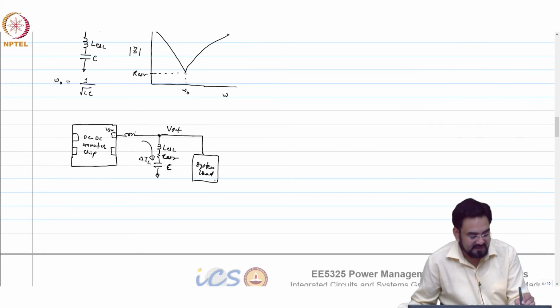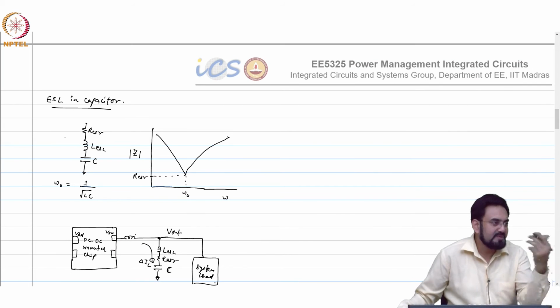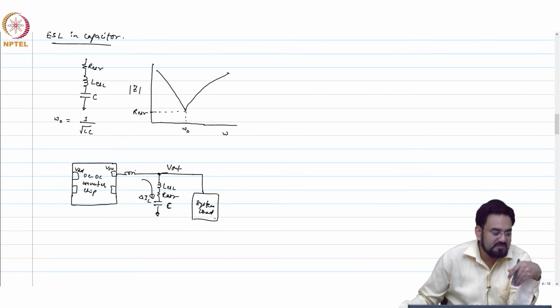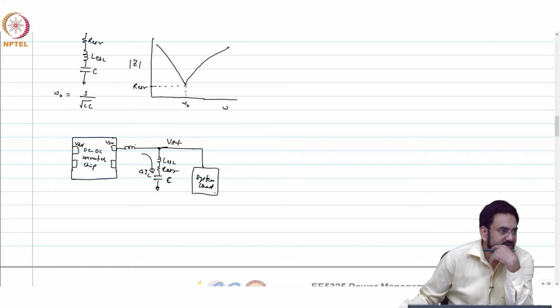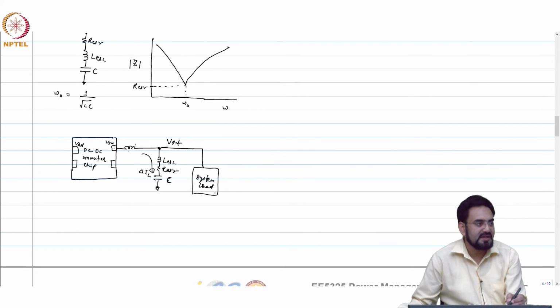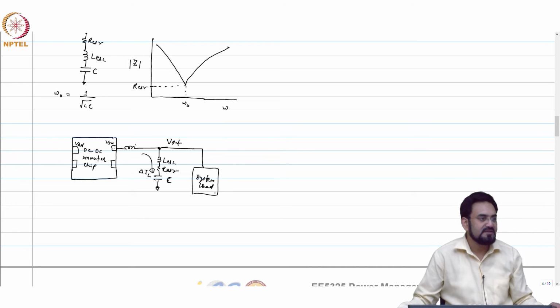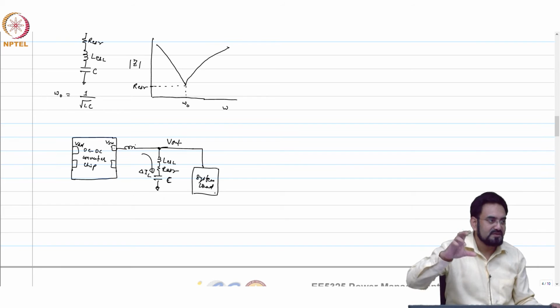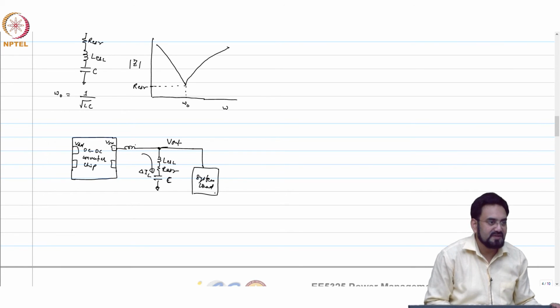And when you are looking at the VDD side, so if this is your VDD, and you know what the current profile at VDD will be, we have looked at it. That will be like a pulsing current, completely on and off. So you need an even more effective cap here, because the ripple current here is continuous, but you have more discontinuity on the VDD side, and the amount of switching current flowing out of VDD is much larger.